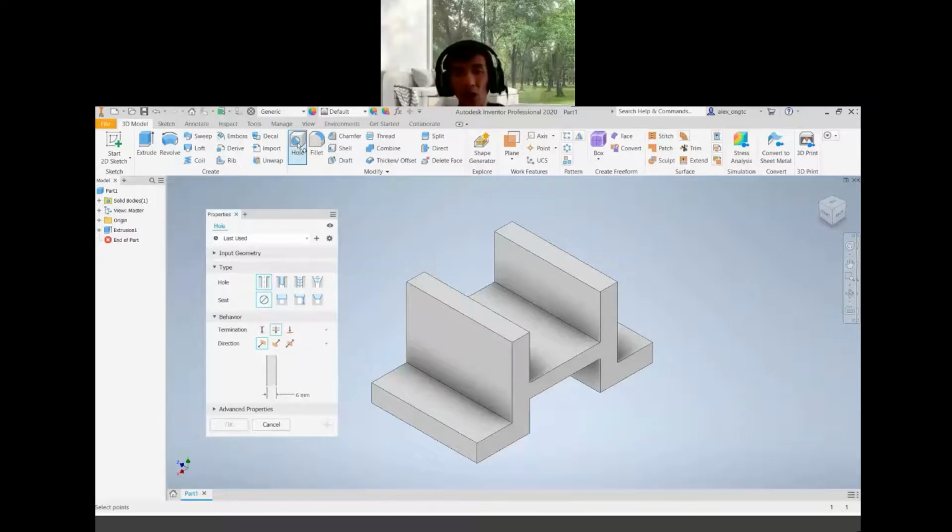Okay, there are various types of holes that you can apply. The first one here will be a linear placement. What we call a linear placement here. So, linear placement. First thing, you need to define the surface you want to create the holes on, as I mentioned to you earlier. If you are lost and so on, please pay attention to your status bar.